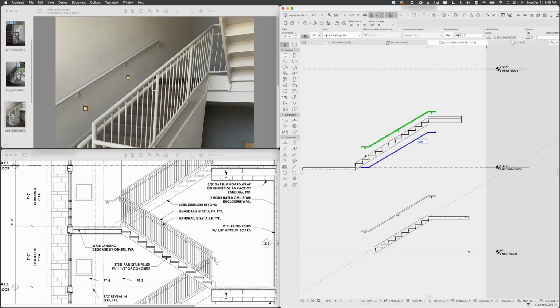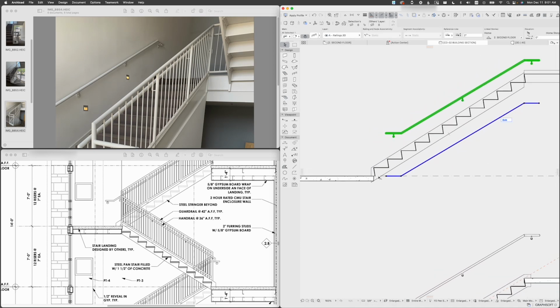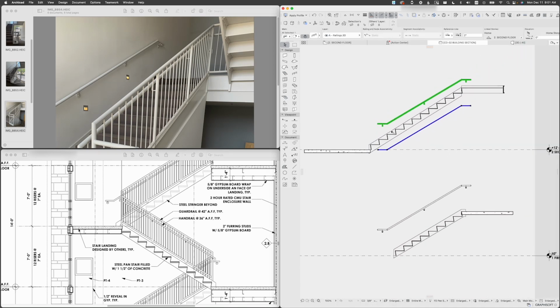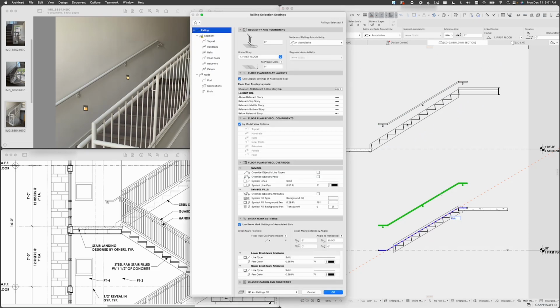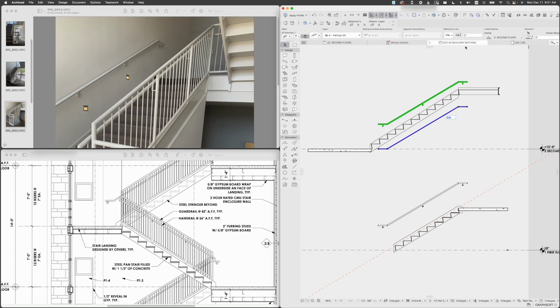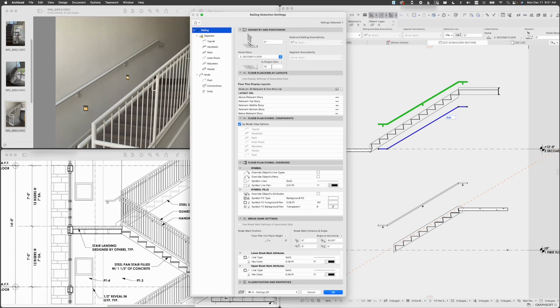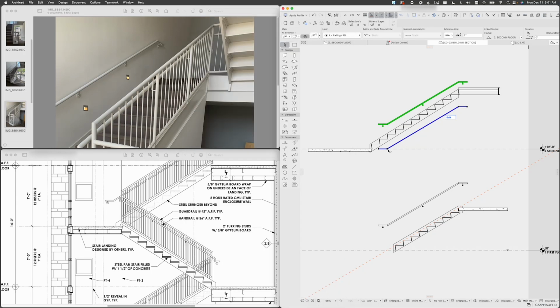And this time, all I need to do is, you see when I've selected it, it is lower than it's supposed to be. Let's see the height of it. Okay, it says 0, but this one says 12 to project 0, so I should change it. I could just pick it and move it.